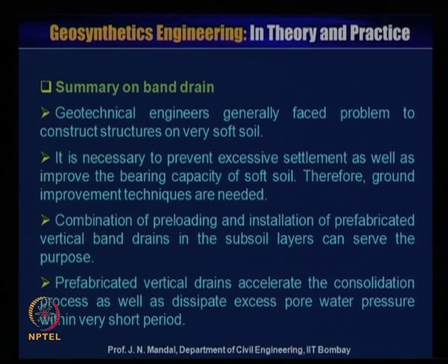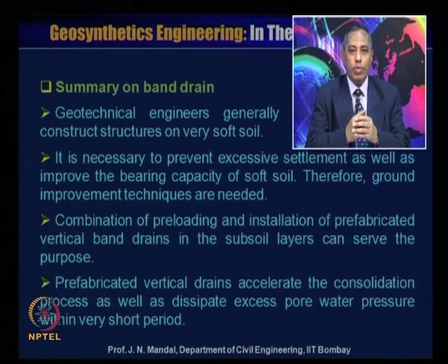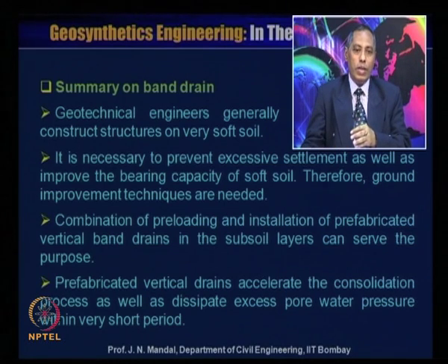So, summary of the band drain: geotechnical engineers generally face problems constructing structures on very soft soil. So it is necessary to prevent excessive settlement as well as improve the bearing capacity of soft soil. Therefore, ground improvement techniques are needed. A combination of preloading and installation of prefabricated vertical drain in the subsoil layer can serve the purpose. Prefabricated vertical drain accelerates the consolidation process as well as dissipates excess pore water pressure within a very short period.